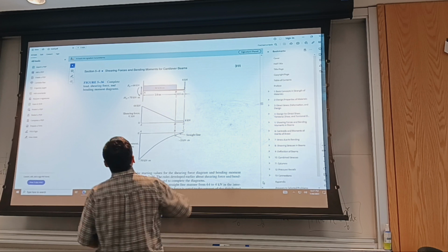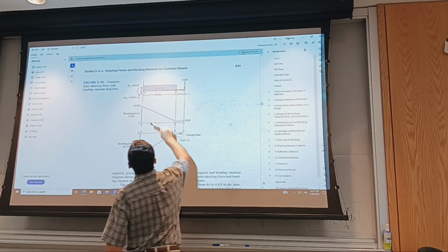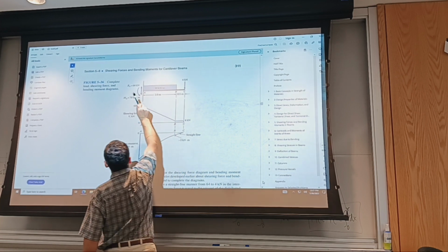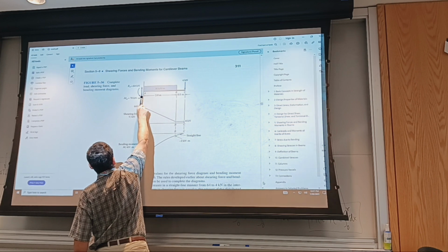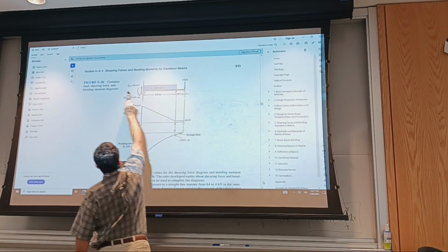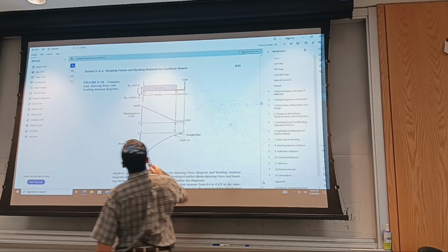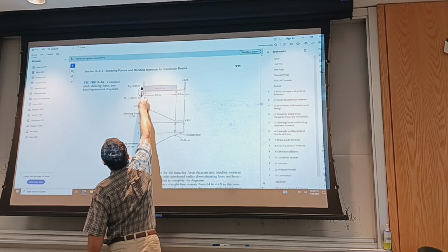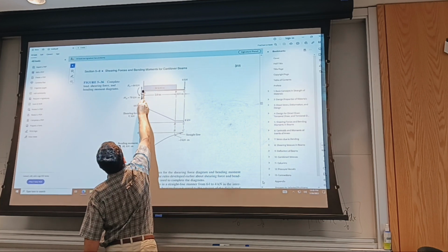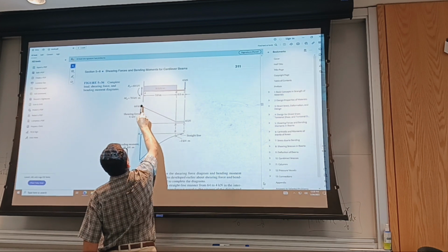All right, but if you have a cantilever, remember, firstly, get the reactions at the support. There's always going to be a moment in the reaction force. If this is at some angle, of course, you need to balance it at the support. And then, assuming this is positive, you have a jump in the diagram from nothing, I can assume an inch of free beam. So nothing, jump, and then linear